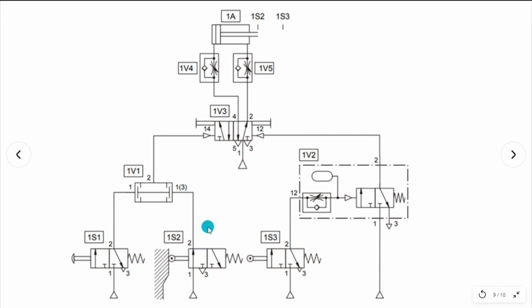So you have switch 1 as your push button, and when you push your switch, and your roller is positioned on its retracted position, so when the piston is retracted, it is actuating your roller lever. So in this case, when both switch 1 and switch 2 are true, using your dual pressure valve, it will send a signal to your final control element.